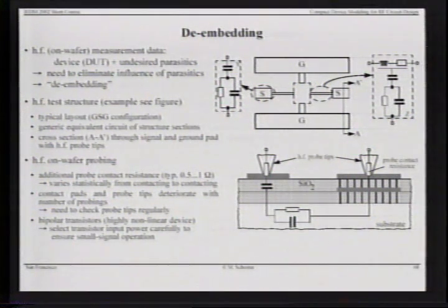Usually you might think that, well, why don't we just move the pads into the highest metal layer? That is something that you can really do if you have to, let's say, if you want to measure up to 100 gigahertz. But in many cases, you want to pull out the wafers early. You don't want to go through all the metallization steps in the fab and wait another 4 weeks until you get the devices out. So many times, people put the metallization into metal layer 1 or 2, and then you have to cope with all these parasitics much more seriously than if you pull it up to a higher metal layer.